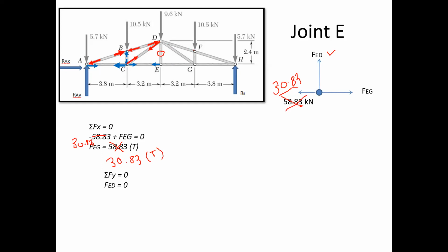Now you can ask how you are going to finish this example, sir. Just observe this given truss. First, observe all the support conditions. Here the value of Rx is 0, so do not consider this Rx. Just think about RA and RB. Both are the same, both are 21. Correct. It means the support conditions are symmetric here.